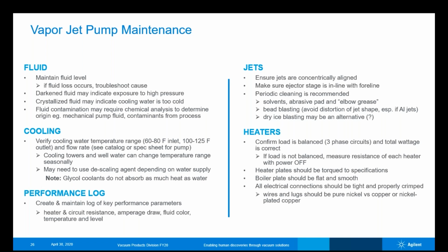Finally, the heaters. Since this is a process that requires heat to boil the oil, or to vaporize the oil so that that jet stream can form, we need to make sure that the load is balanced on three-phase circuits and that the total wattage is appropriate for the heater style that we have. If the load's not balanced, we want to measure the resistance of each heater with the power off and look for any faults or shorts in that system.